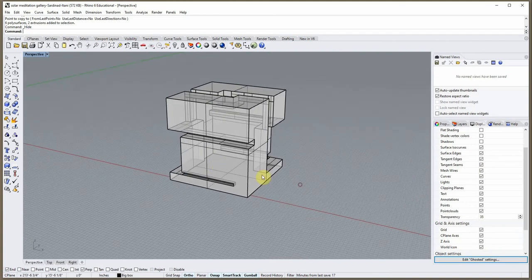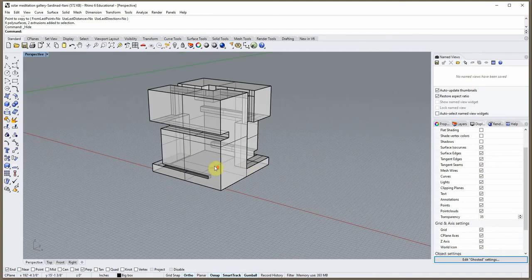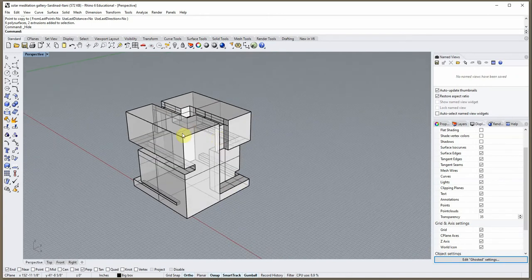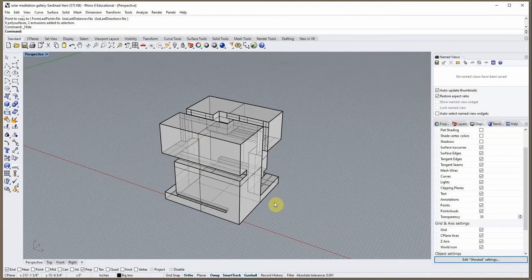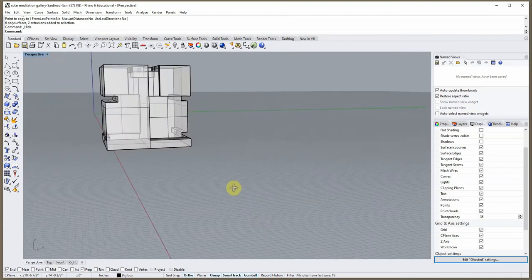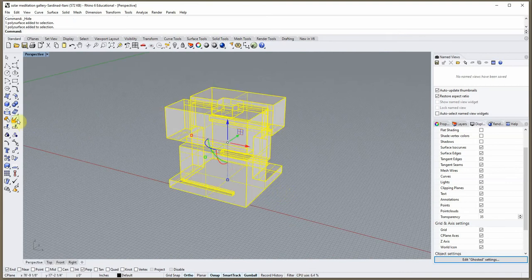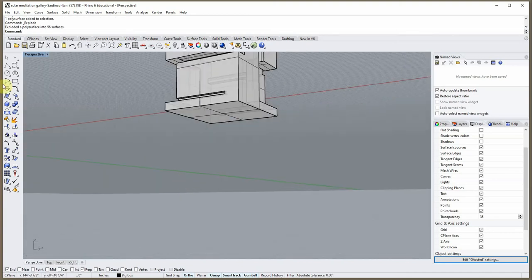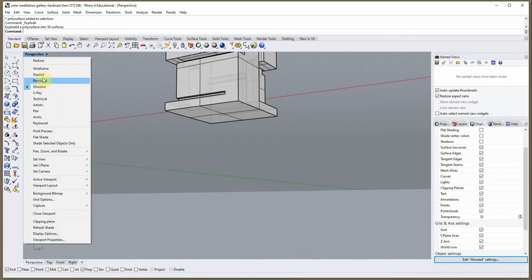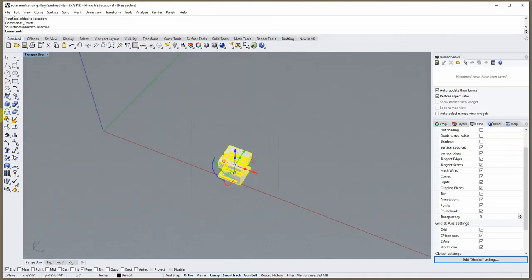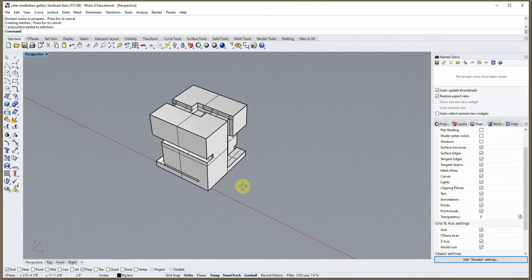We rotate a lot. So since I'm going to be trying to make some decisions in terms of the interior spatially, where I'm going to put my pedestal, where I'm going to penetrate the roof or the walls for these sun angles, I'm going to need to know where the floor is. So I'm going to proceed to place a floor in here so I can get inside the box. First step for me is just to explode this first and get rid of, let's go to shaded mode for a second, delete the bottom floor. Once you explode it, you definitely have to come back and union it. Otherwise you can't do certain things to it afterwards.